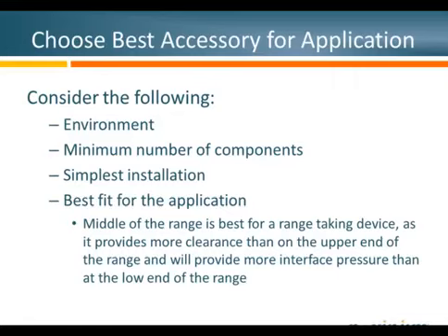And one other note about environments: if you're dealing with a joint, you want to consider whether it's going to be aerial, up in the air, or direct buried, or in a manhole, and if the manhole is full of water, and if the manhole sometimes sees hydrocarbons or not. So all of those things you have to consider and then choose the best accessory for that environment. And again, a simple installation is best because then it's going to reduce your number of steps, make things simpler, and therefore easier to install.